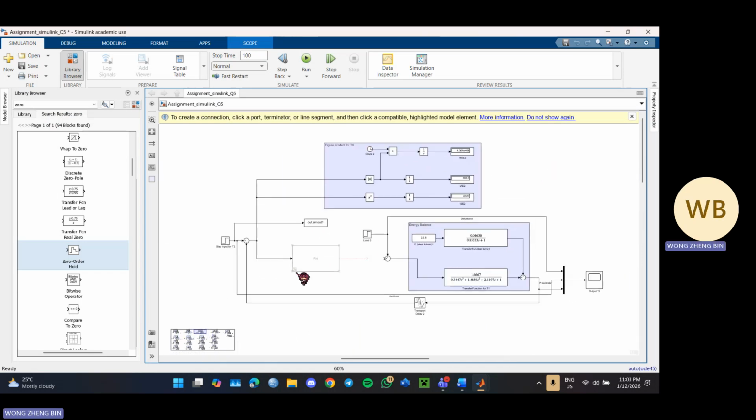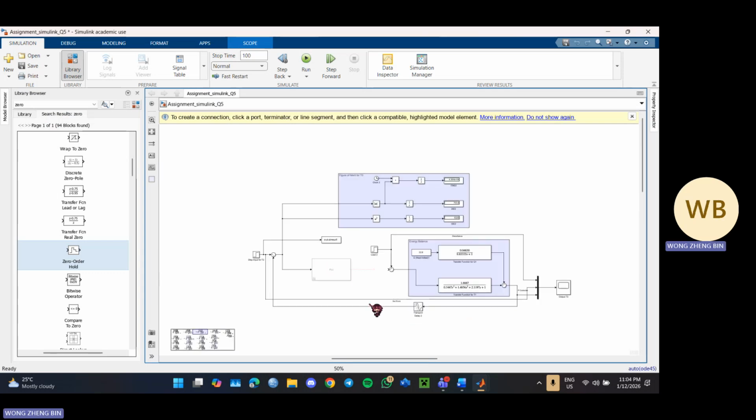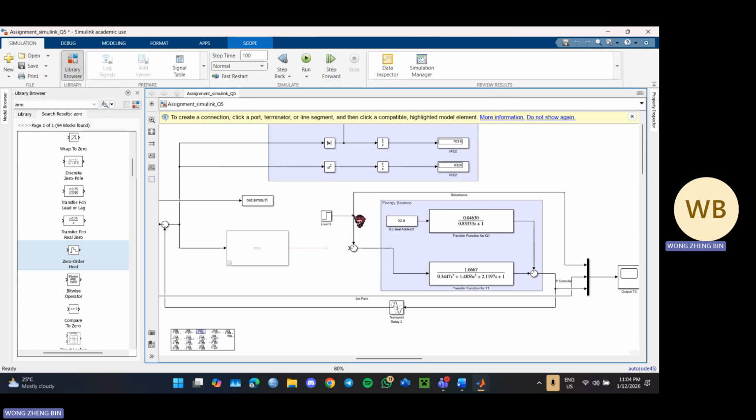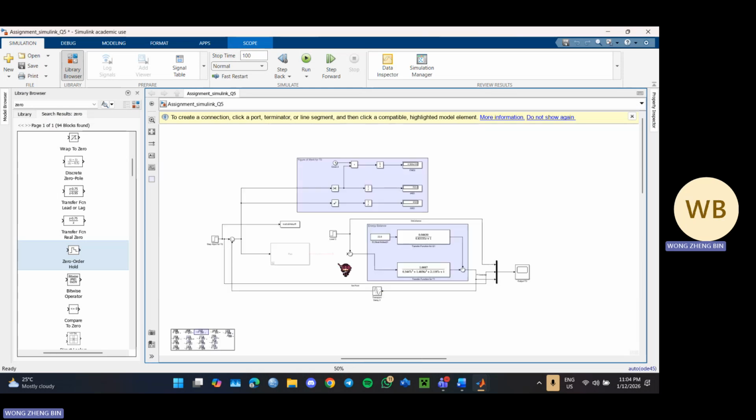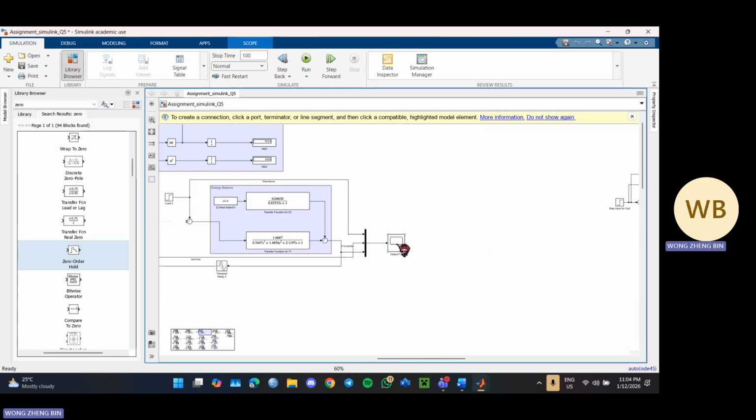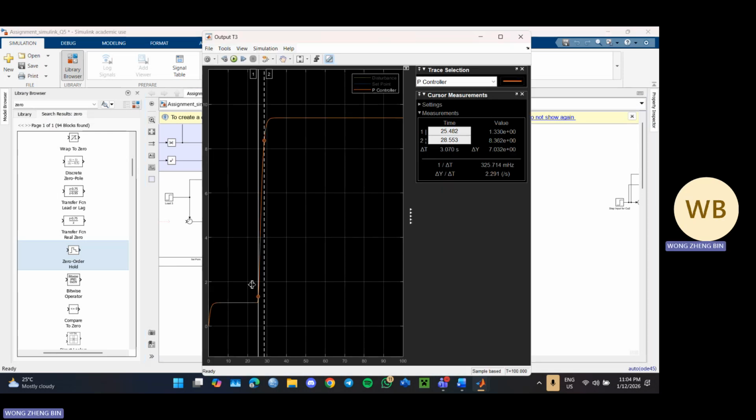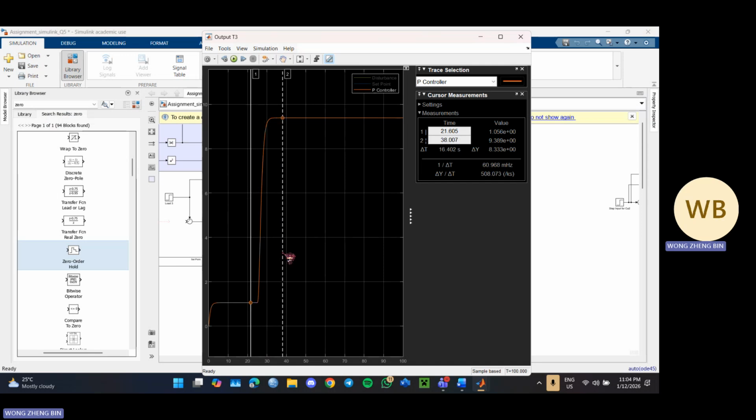As you can see, the controller is out of the equation, and then we input a set signal to get the graph. So you can see that the reaction curve is like here. When the process reaches the steady state, after we input a signal, it rises again to get this S shape. So then we can get all the parameters in this S shape.